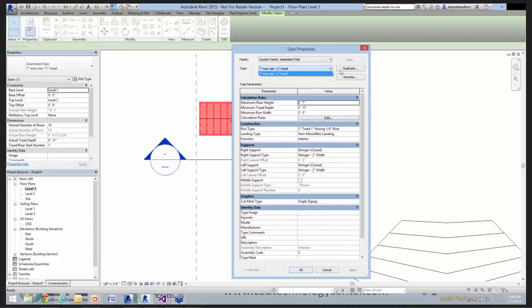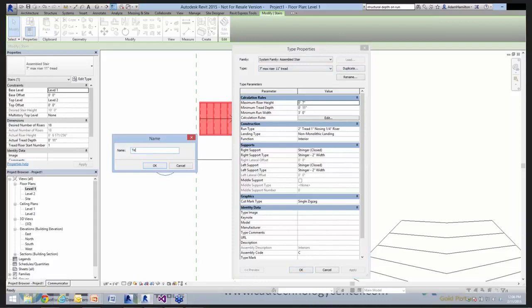You want to be able to grab those elements and copy and paste them into the next one. We don't want to overwrite things. We don't want to modify it, because there might be elements in there that are already set up. You may have already created some things, and you never want to overwrite something and have to wonder what changed. Did something I brought in change? Did something I overwrote change? And have to double check everything. So always duplicate and create a new type. For what we're doing right now, I'm just going to create a test.